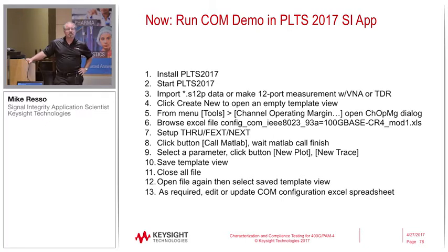In that sort of situation, I think I would use the 12 standard COM configuration spreadsheet, but then I would go ahead and say, you know what, I know these other channels are going to give me crosstalk just by looking at the geometry of the connector. So I'm going to do a higher port measurement, or I'm going to use the round robin method, and I'm going to create a larger S parameter file from smaller S parameter measurements. So 12 isn't always how many ports you have for the COM.